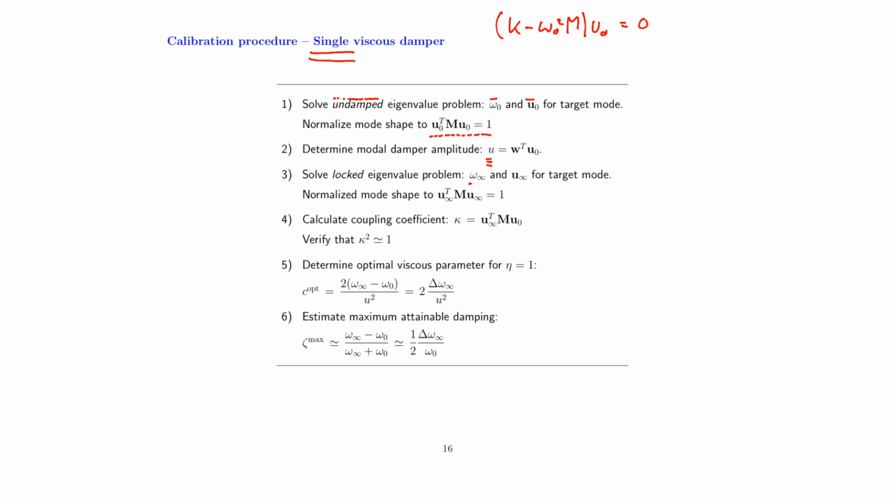Then you're looking for the infinite natural frequency, and that you'll find by solving the eigenvalue problem. So that means you'll find this K infinity minus omega infinity mu infinity. And remember that this K infinity was your original K plus your stiff spring multiplied by your outer product of the connectivity vectors, in this case only the single connectivity vector. So you have to solve 2 eigenvalue problems to make this analysis, and remember to establish your infinite spring stiffness matrix in this way.